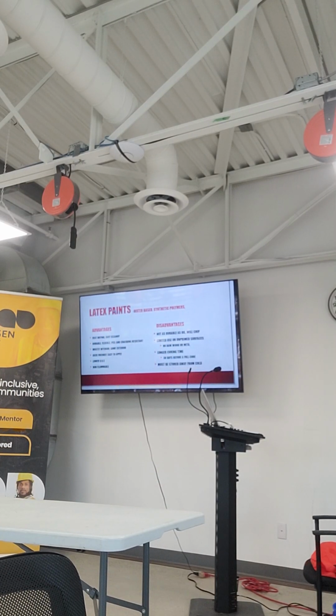This is a 2K polyurethane. What this does is this stuff cures as it dries. So it's called a self-sealing material. So we did a stretch test here. That's the primer underneath it. The primer won't scratch off. It's bonded fully to the surface. And that happens in 24 hours, as opposed to using a latex, which, like I said, takes 30 days.